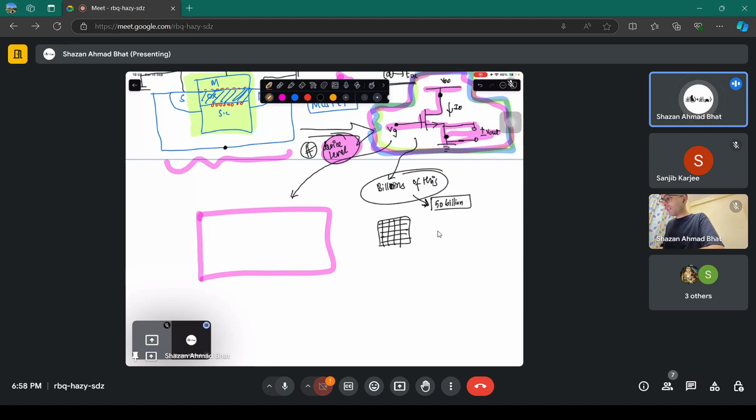Just a basic representation. If you have this single MOSFET which I showed, this is the drain voltage, this is the source voltage, this is the gate terminal. Why are these two plates shown like this, with a space between them? Because in between there's a dielectric. So that's why these two plates are not shown connected in the representation. Okay, don't get confused with it. You don't connect these two plates in the symbol because there's an oxide between.